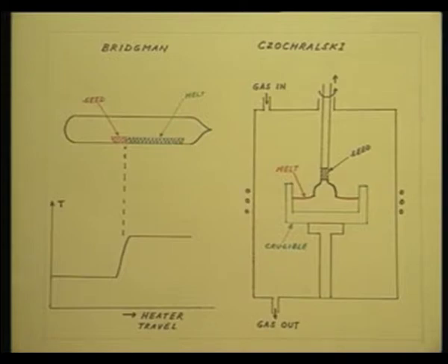Alternately, you could also move the quartz ampule in this direction. Same purpose will be served. Instead of moving the heater, you could just move the quartz ampule in this direction. Even in that case, the seed end of the melt will come into the low temperature zone, and therefore, it will get solidified in contact with the seed crystal. It will get solidified as a single event and will realize a single crystal.